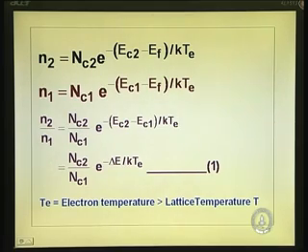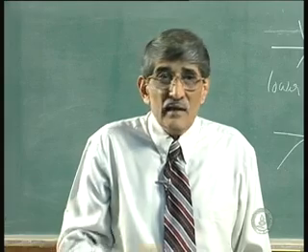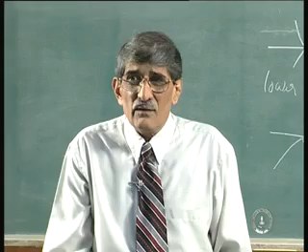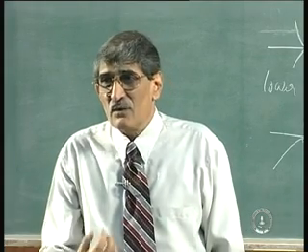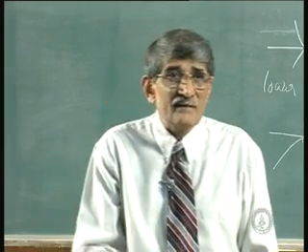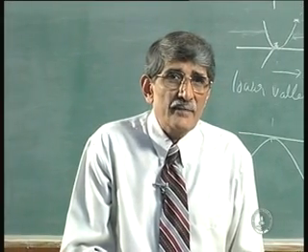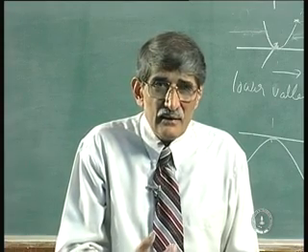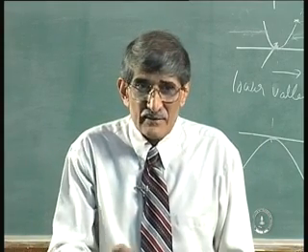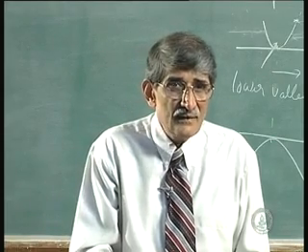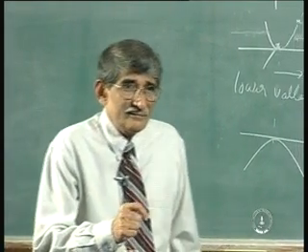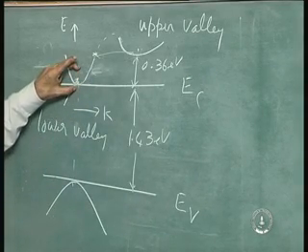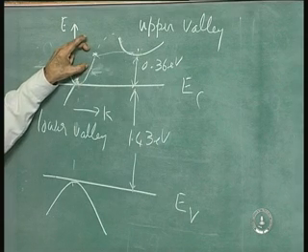Like when, in the Schottky barrier, we talked of an electron being injected into the metal with higher energy than that of the metal, that is a hot electron. Here also you are talking of a device in which the electrons are hot. When you say electrons are hot, I repeat whatever I said earlier. The implication is the electrons have energy in excess of kT, corresponding to temperature T, where T is the lattice temperature. If it were T, the lattice temperature, it would have remained here, distributed up to a certain height, but they are taken up to a higher value.